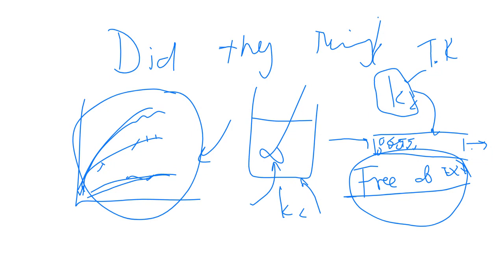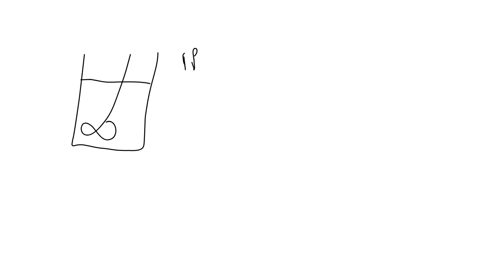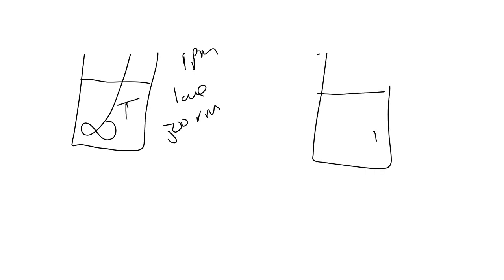And how do you do that? You investigate some of the information that I publish later on in some of the later videos on the combined effects of all these mass transfer resistances. If you do 2 runs, one at low RPMs, so you stir at a lower RPM, let's say 500, and then you do another run at exactly the same temperature, with your catalyst particles and everything exactly the same, but you stir at 1000 RPMs.